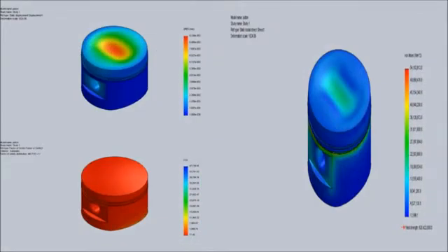The stress analysis for the piston made of alloy steel shows that under a pressure of 4 meganewton per meter square on the top of the piston, it had a maximum stress of 18 meganewton per meter square, an average stress of 5 meganewton per meter square, a maximum displacement of 9 micrometer, and a safety factor of 11.5.